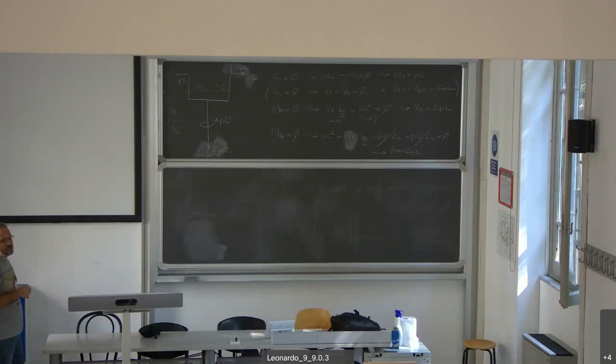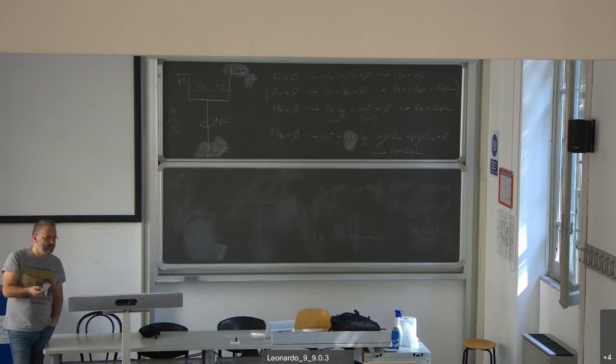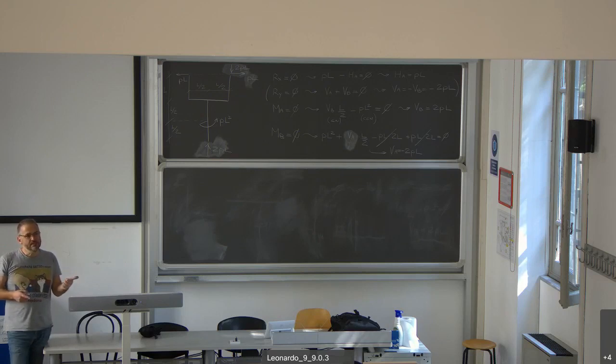Which basically means, what should I expect? Axial force will be either 0 or constant along the members. Shear will be either 0 or constant on the members. So both axial force and shear force will either be 0 or rectangles, constant diagrams of internal forces.